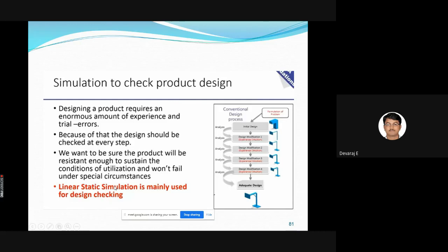Because of the load it should sustain, right? It should not go beyond 90 megapascal, considering the factor of safety, the FOS. So it should not go beyond 90 megapascal, right, students? Yes, sir. First we'll check the linear static analysis.